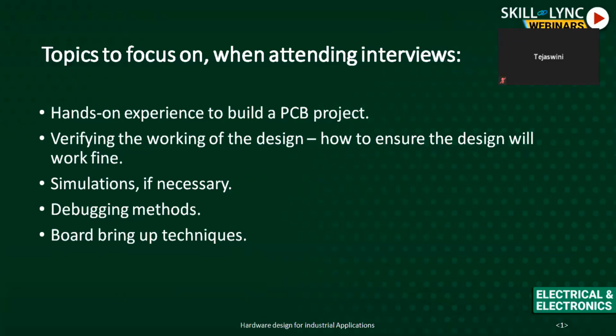Simulation tools are again LTspice, MATLAB, and so on. We need not know them at a very deep level, because once you go to the industry, they'll give you the training, but it is good if you know them at a very basic level at least. Then the debugging methods: how to debug a power supply, how to debug a microcontroller, a clock circuitry, how to debug a load, whether the type of load is applicable to this particular circuit or not. Then board bring-up techniques, like I explained, you have to go in sections and check each and every section by giving the power supply, and then finally you can put everything together.